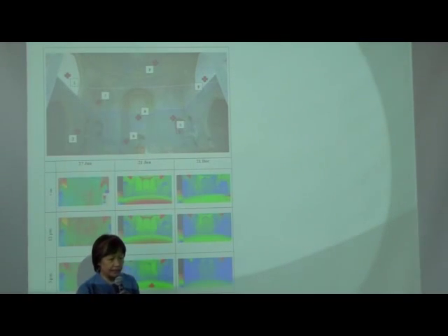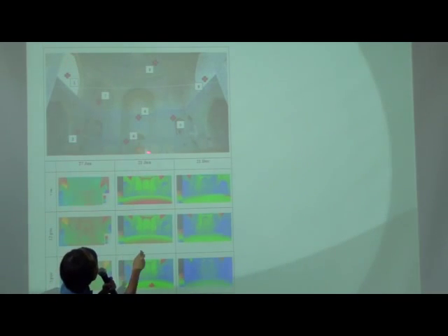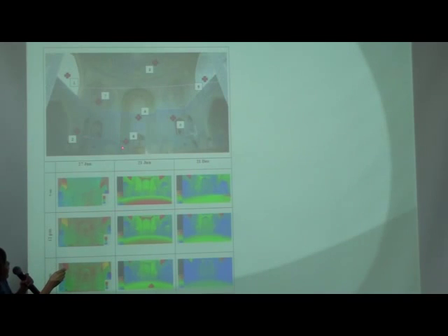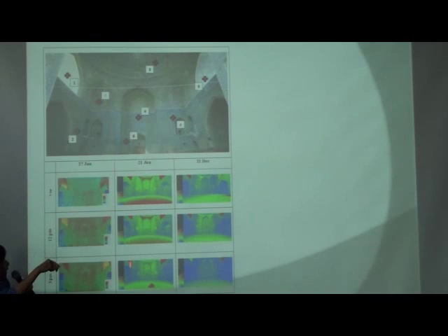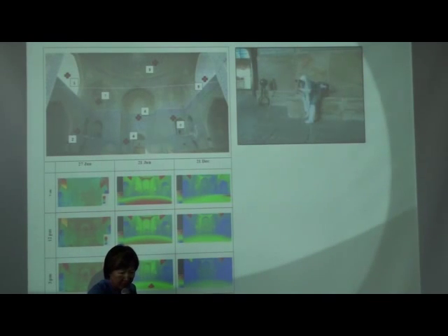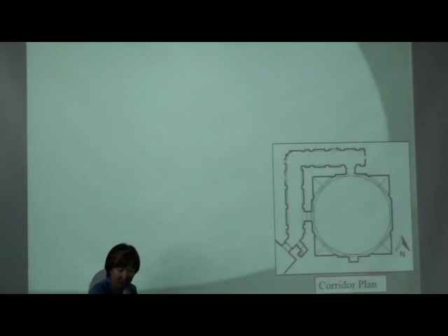Okay, and then using the photograph luminance meter to analyze, she used several tools. A luminance meter to analyze the brightness, comparing with the HDR image to validate if the quality of the photo is usable. So, interviews together with the measurement and analysis of architecture and material, you see the process.